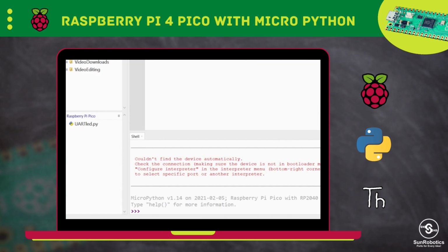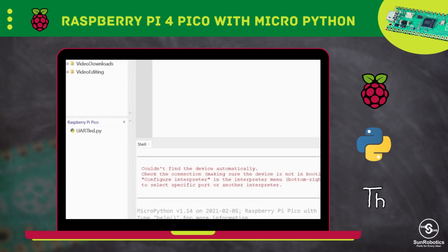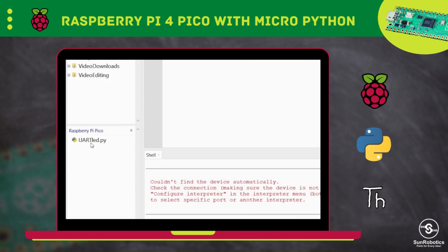Let's start with some commands. For that you need the SDA pin and SCL pin. Then I will make a complete program in the editor portion. For that we have to import something called machine. And there is a library required to run our OLED display. That is very important in this case. So you see here in the Raspberry Pi Pico there is only one file, that is led.py, the one I tested. This is the only file in the Raspberry Pi Pico.